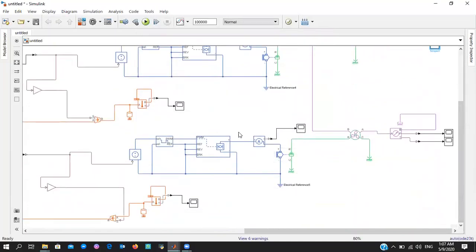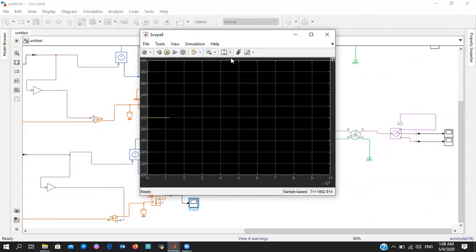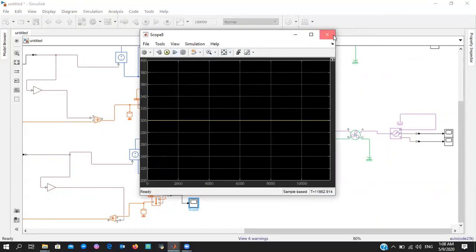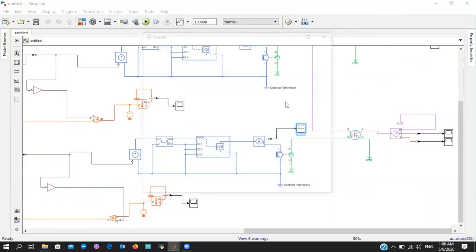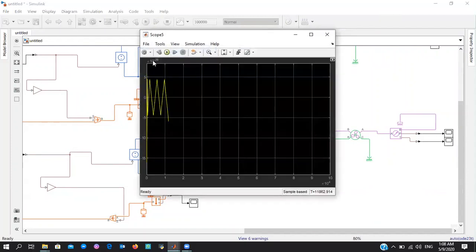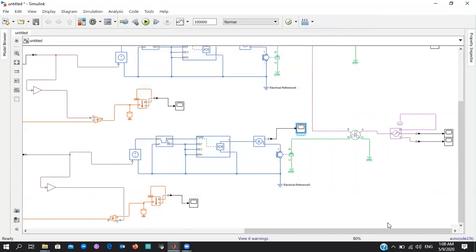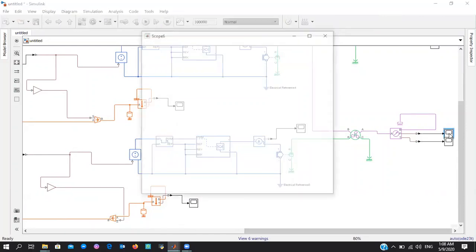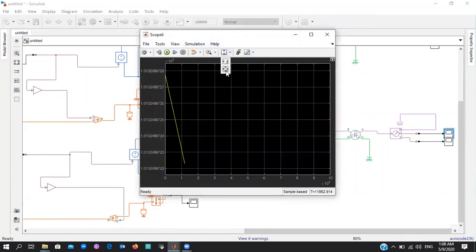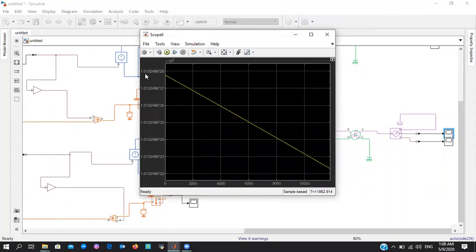Now, this did not work at all, this part, the heating part. As you can see, this temperature is still the same, 300. This current is actually times 10 to the power of minus 26, so it's actually 0. And here you can see the pressure stayed the same. You may see it dropping, but look at the values, 1.01324999, and here 1.01324999, so it's actually the same.